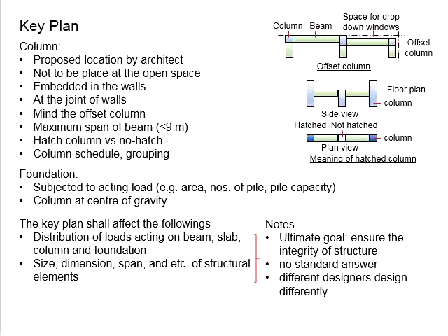You have so many reinforcement bars that you have sufficient space within the wide beam, but when it comes to the joint between the beam and columns, and there is another beam incoming from the perpendicular direction, you will have problems with the congestion of the reinforcement bar at the joint, which is quite difficult to handle on site. It is only used when you cannot find any locations for additional columns, especially when you're not allowed to put any column in the middle of the open space.